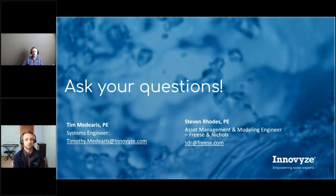There's probably not going to be quite as much head loss through that because the manhole is usually built around, or at least in this case, the manhole is built either on top of the pipe or around it. So it's not really like it's hitting this static volume of water. It's just kind of continuing right through the structure. So sometimes those entrance and exit head loss values are a little excessive.